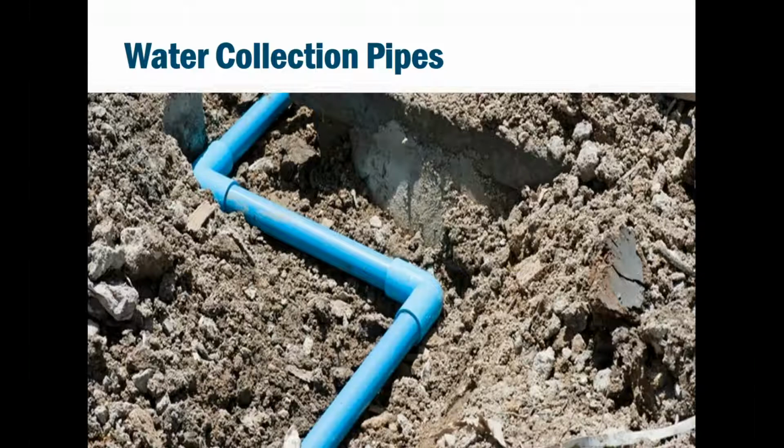Providing a wrapped perforated pipe is typically not recommended unless the base is clean. It may be better to provide a geotextile filter around the perimeter of a drainage trench with the pipe encapsulated in that clean stone. The main thought is to prevent clogging, and the method used is going to depend on the stone type. So you can have a nice flat parking lot and still drain your stormwater with ease.